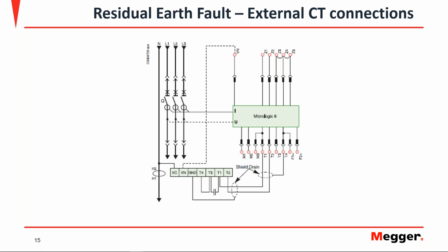In this particular example, the manual tells us that if the supply is via the bottom, then you have to wire the external CT a certain way, and of course if the supply is at the bottom, you have to not only reverse these connections but also change certain connections here for the control. So it's really important that we understand the CT polarity and the proper connections according to